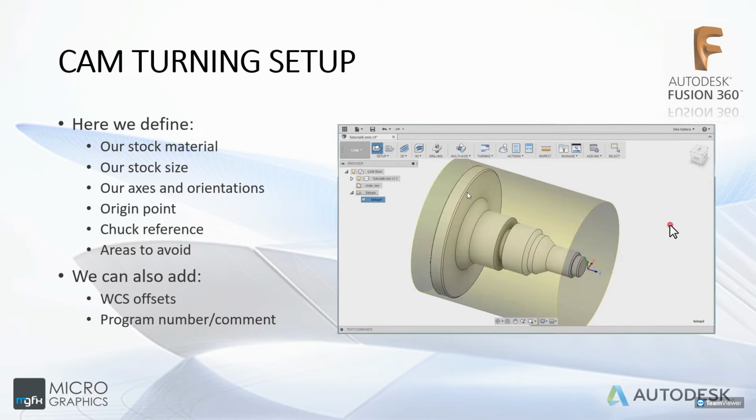You've also got to tell it how much bigger than your model that you've drawn is the stock. Meaning you can see here that the translucent yellow bit sticks out a little bit more than the model. So it's not the exact same size. You've got to mill it down a bit to get to the outermost area of your model, and then start milling inward, inward, inward until you clear most of the material and get the shape that you want.